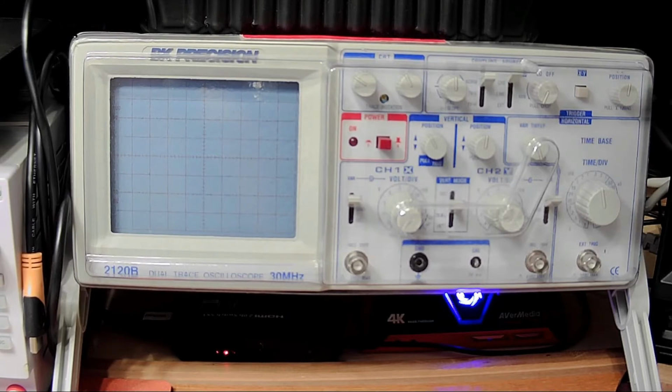On a digital oscilloscope, if you've got an event that doesn't occur regularly but might only occur once every now and then, you can set a trigger on it, do the single, and then you can analyze the waveform on the screen. So you really need both. I feel I need both.